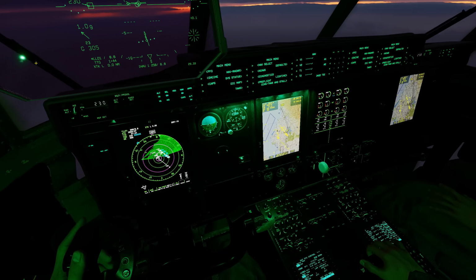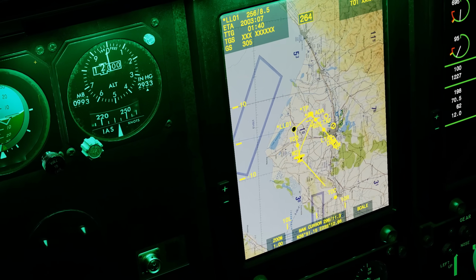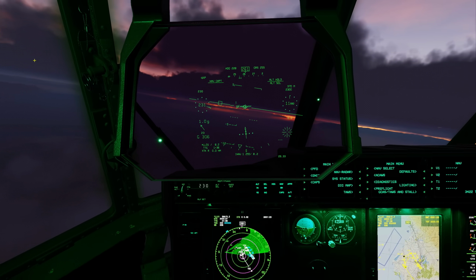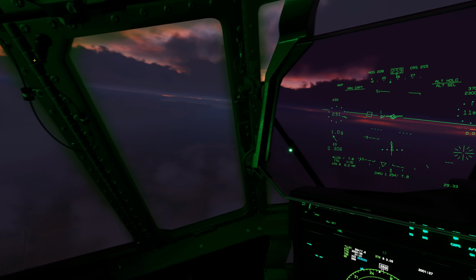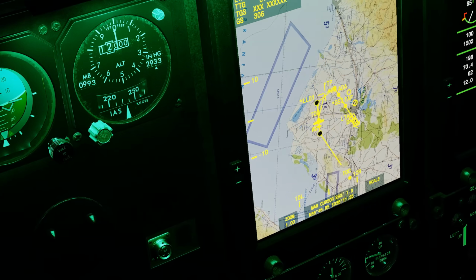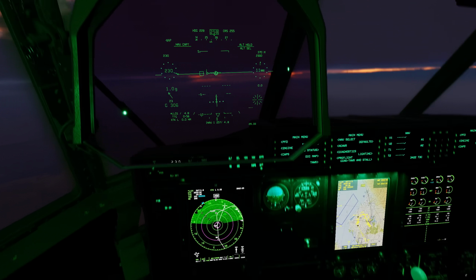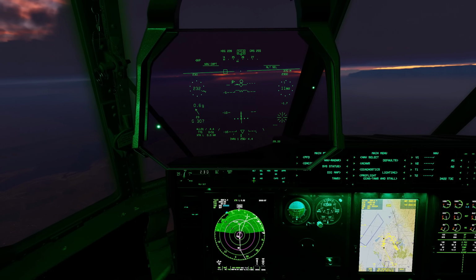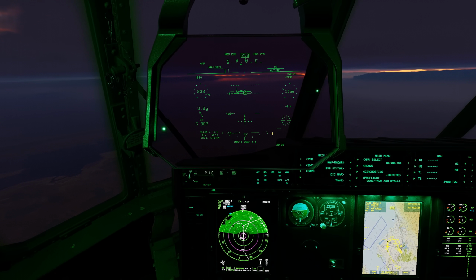Alright, well, looks like we made our first turn. And top of descent is coming up here shortly. I'll pitch sink us down to about 5 degrees. Alright, as soon as you do that, I'll ask you to pull the chart up. I want to get the VOR punched in. Roger. Alright, reaching our TOD, I'm going to pitch sink us down. Copy, descending. VS is set.